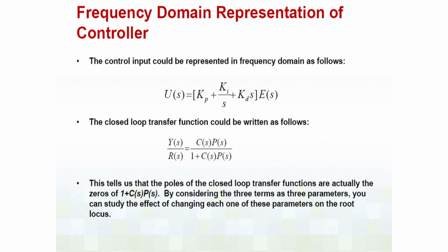So, in the frequency domain, this will look like what? The integrator will become 1 by s. So, it will be Ki by s, and the differentiator will be Kd s. Now, if I try to find out the input-output transfer function of the system, remember many times we write it with different notations, but it is the same: it is the compensator times the plant. Sometimes we write the compensator as C(s) and then the plant as G(s).